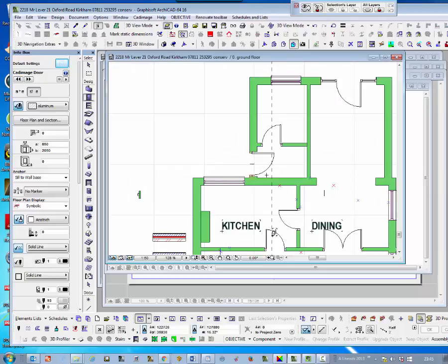With that being an external door, we shift click on it, it should be off the cavity, which is in the middle of the wall, and to do that we offset it by using this tool over here, 110. You see it jumps into the middle of the wall, so that's correct now.